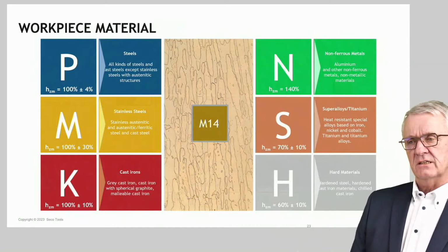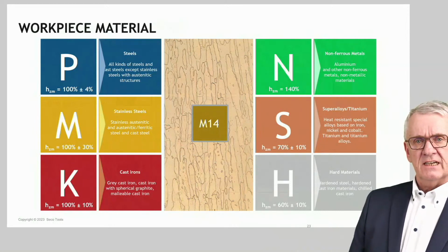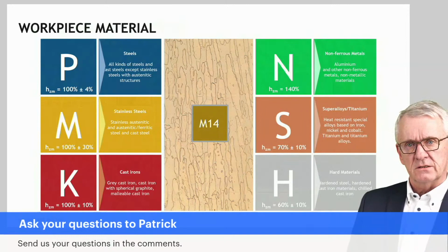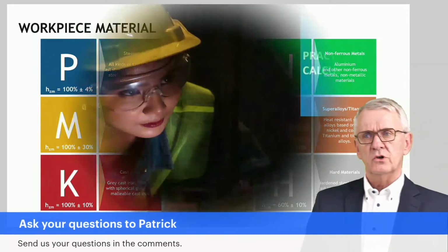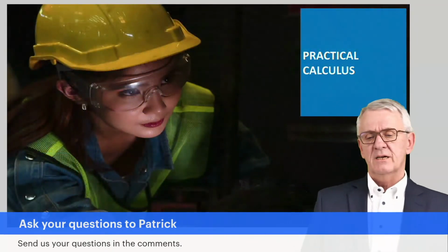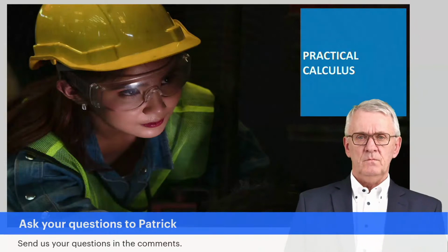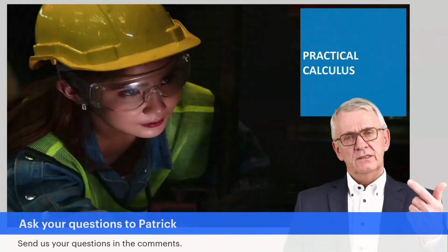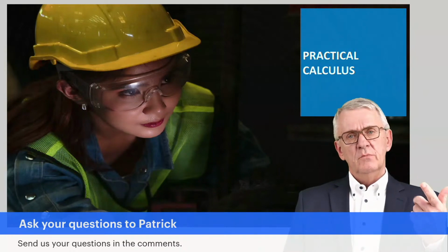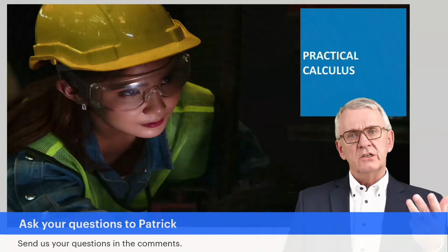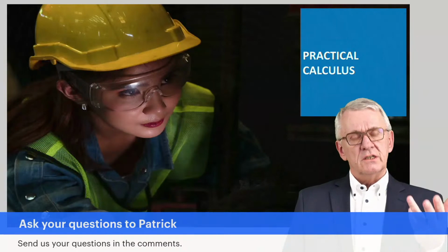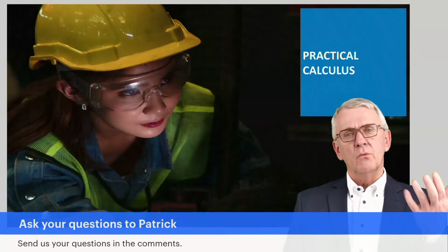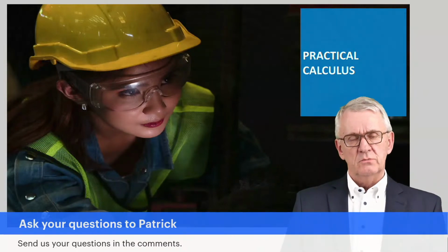And that's why it says here in the diagram, you should take that 18 hundredths of a millimeter and take only 60% of it. That's to compensate for workpiece material properties. And those are the variables: radial depth of cut, diameter of the milling cutter, positioning, the cutting edge angle you use, the cutting edge geometry you use, and the workpiece material in which you machine.